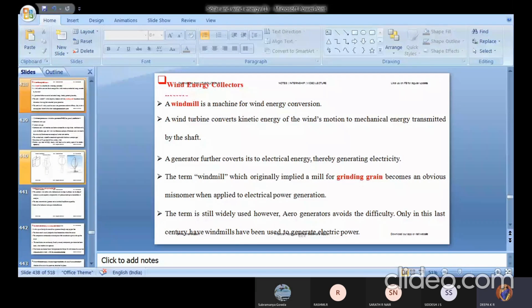But if the blade length is more than 60 meter, mounted on the rigid hub, large blade root bending moment may occur due to the tower shadow, gravity, and sudden shift in the wind direction. If it is very, very lengthy, balancing the system is very tough. It can be a problem due to gravity, or it may fail due to the high input throwing on the system. So you should be careful about the system with more than 60 meter diameter.